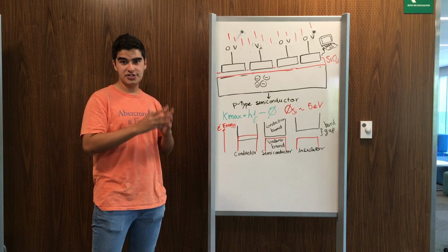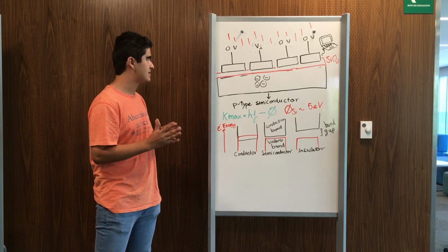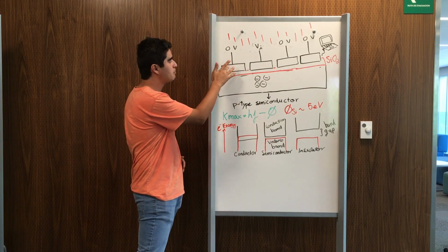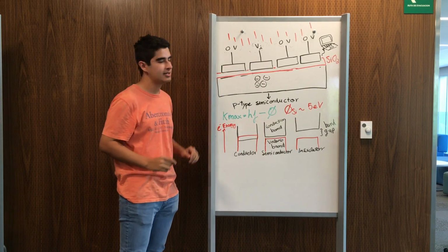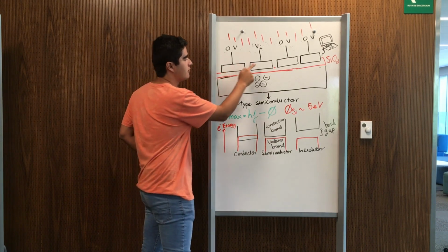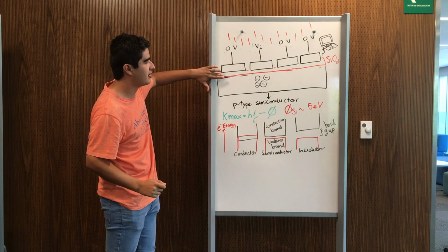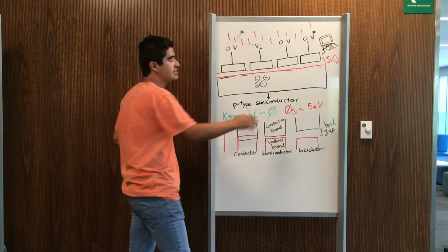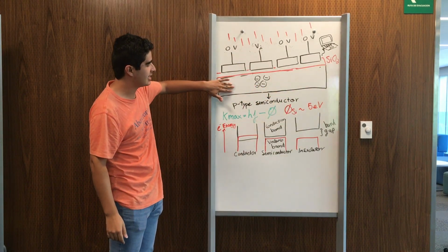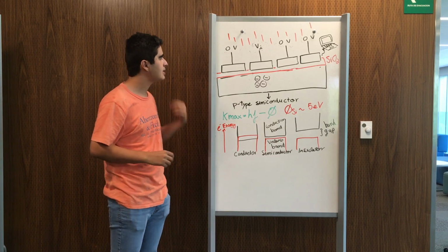The sensors used in the spectrometers are CCDs, or charge-coupled devices. These sensors are composed of three main layers. The first one is the layer of pixels, which is composed of different electrodes. The second one is a layer of insulator, which is composed of silicon dioxide. And the third one is a layer of semiconductor, which is usually made of pure silicon.